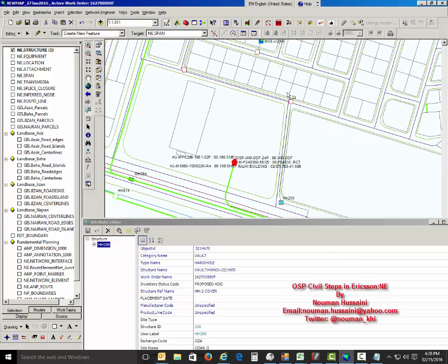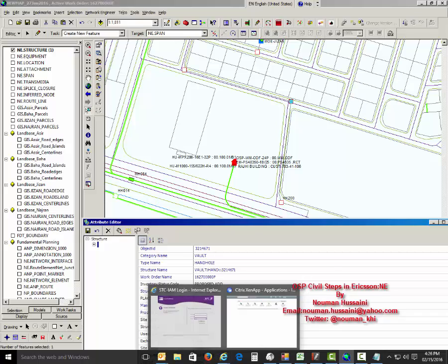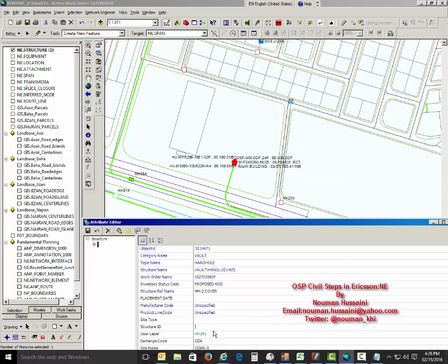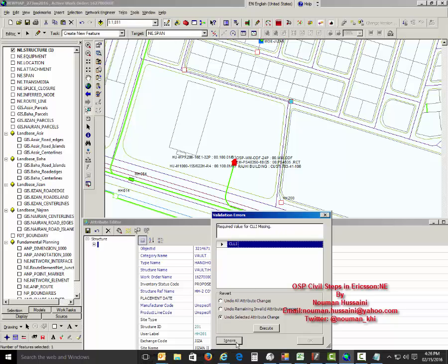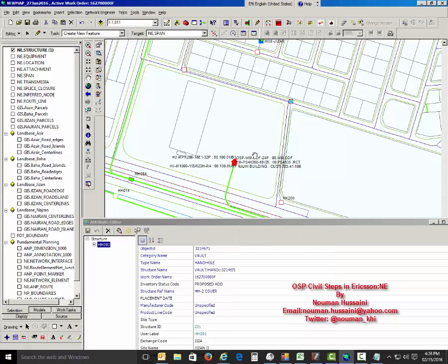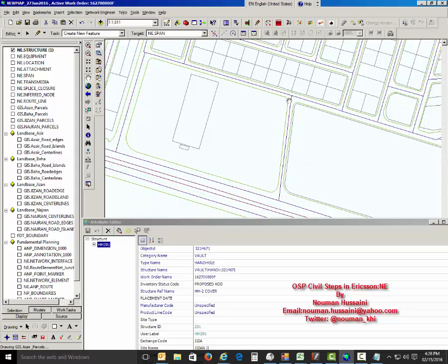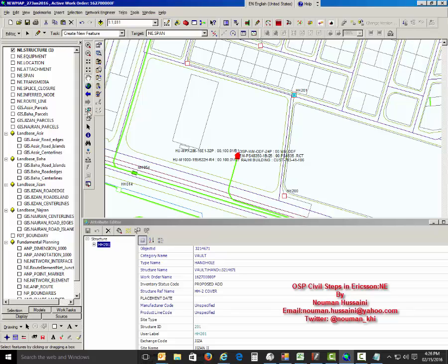Remember, the first step was to locate the customer, place the customer premises, then locate the nearest handhole or manhole, draw our span lines, then place new handholes, then draw a span, then place a handhole, and so on until we reach the customer.